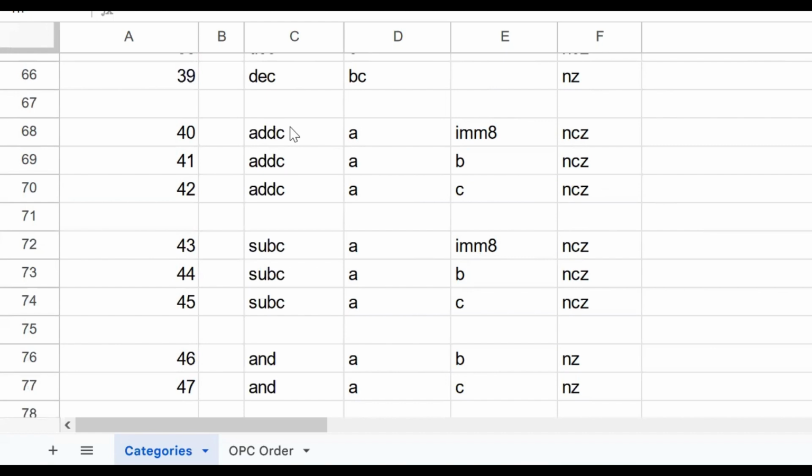We get to the add and subtract statements here. Again, I had to cut back the number of register combinations we could use for the additions and basically the operations. We just don't have enough instructions to do arithmetic and operations on every register combination. Basically, what's provided is